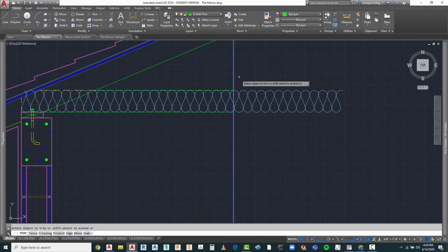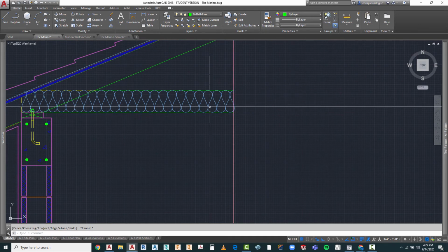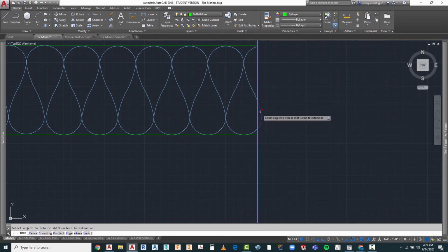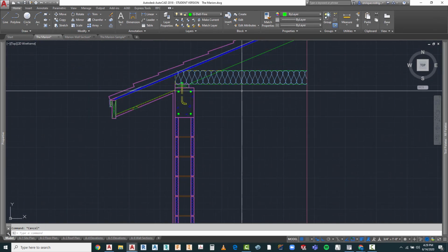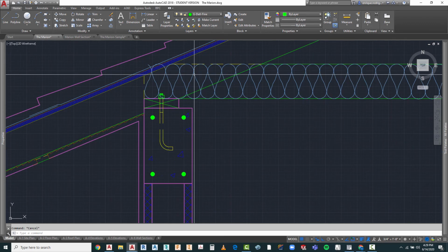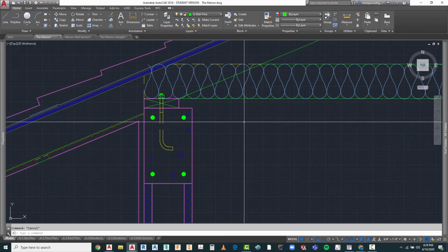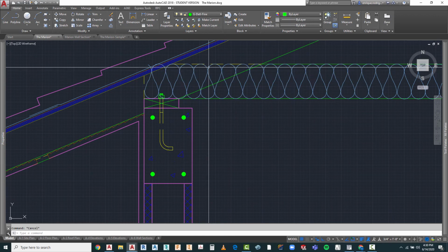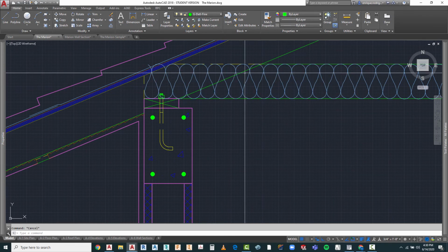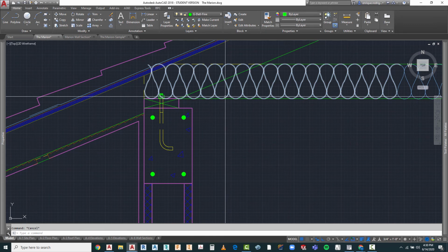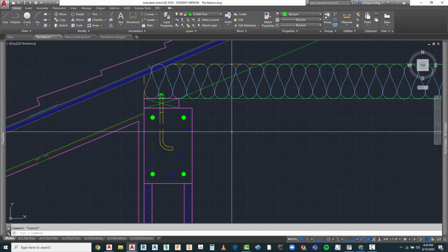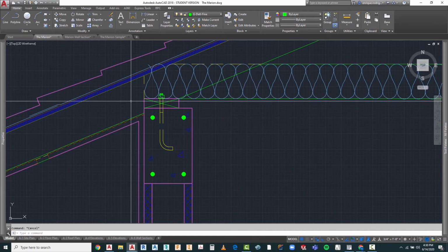Let me see if I can do that. There we go. All right, and that is our insulation. Again, you've probably seen it. It's pink, and it can be itchy, and it actually lays in between either the rafters, the trusses, or the ceiling joists in here. It's got paper on one side, and it's stapled to the bottom surface of the structures.